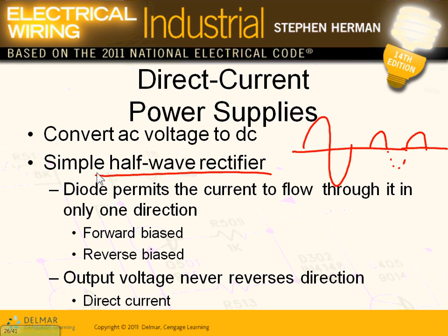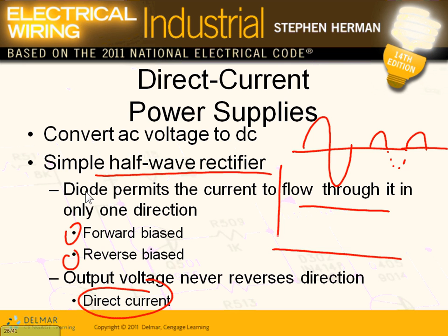They use diodes. They forward and reverse the diode by flipping the voltages across it. The diode is like a valve, to make the current go if it's positive, or plug it if it's negative, and keep flipping the voltages across it. So that's how we get from your AC. The outcome when they do the rectification is always a DC. The whole outcome that you want is always a DC voltage.